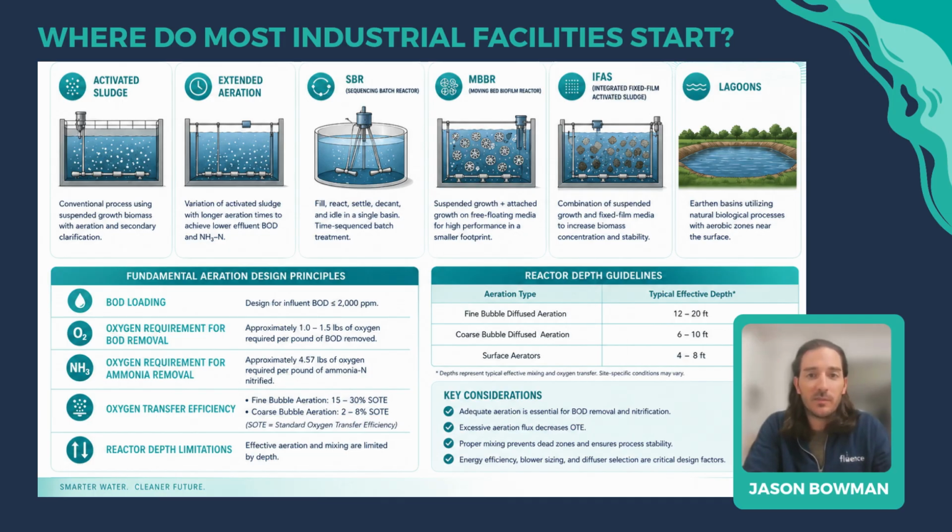Conventional aerobic processes have been around since the early 1900s, and there are even more modern aerobic technologies that came into the market in the later part of the 1900s or even the early 2000s. Generally speaking, these are recognized as reliable processes, but these processes start to lose their effectiveness and economic viability as the strength of the wastewater increases or as the variability of the wastewater increases. In such cases, the energy demand, the excessive sludge production, and the sensitivity make aerobic operations a poor fit in some of these industrial applications.